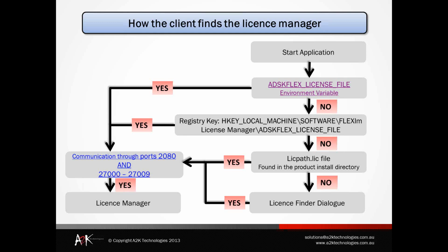When a user starts their application, be it AutoCAD or Inventor or Revit or whatever the case may be, it goes and looks for an ADSK_FLEX_LICENSE_FILE environment variable.